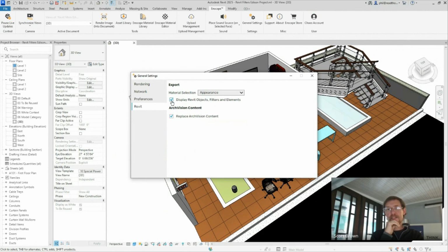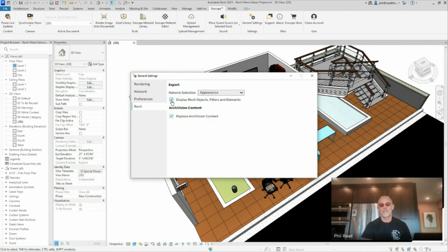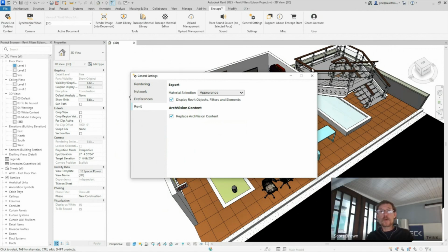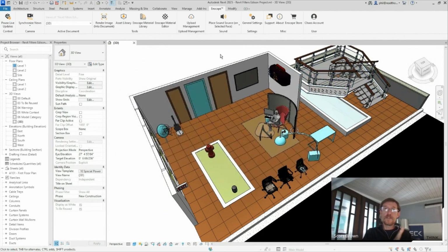It might. And the other thing, Chris, if you try to make objects in linked files transparent with a filter, like we were saying, it doesn't presently work. You can't manipulate the filter of a linked element. But just go through the transparency of the model category. That's where you're getting it. And that'll work on filters or in the host file. It's important to understand that you don't have to use filters if your view template has model category objects overridden with transparency. That's going to come through.